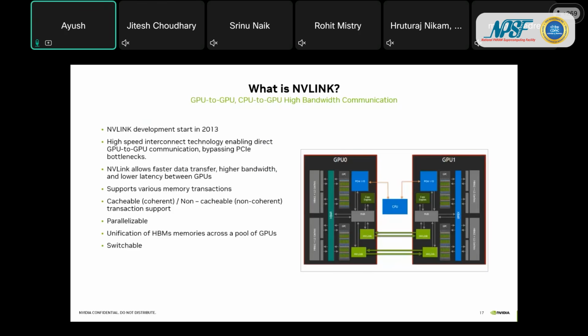So now coming to the point, we are talking about NVLink too much. So what are these NVLinks? Unlike traditional PCI interconnects, which quickly became a bottleneck in multi-GPU systems, NVLink provides higher bandwidth and lower latency. In the fifth-generation NVLink for Blackwell systems, we can get up to 1.8 terabytes per second bidirectional bandwidth using these 18 NVLinks.